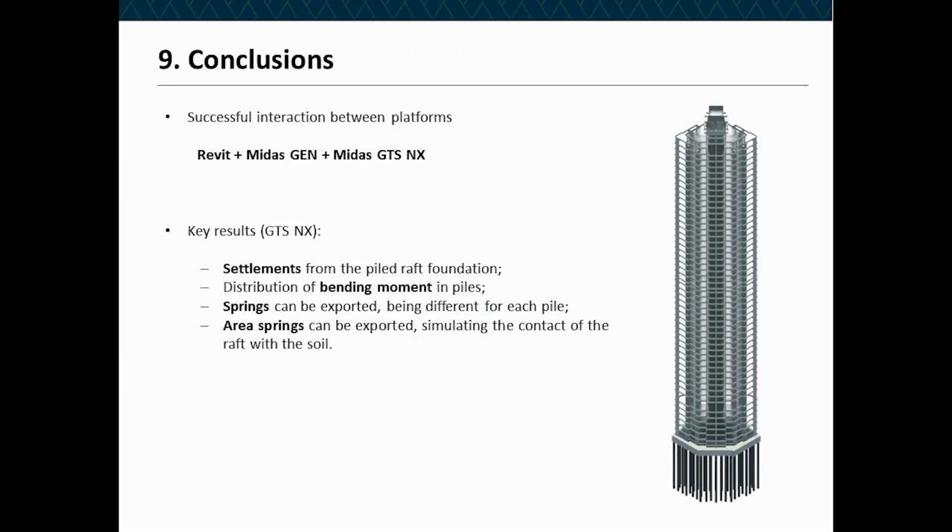Well, for some conclusions, we consider that we had a successful interaction between Revit, MIDAS Gen, and MIDAS GTS NX. The key results from MIDAS GTS that we have analyzed are firstly the settlements of the pile raft foundation, which might be inside the range of the tolerable settlements for this kind of structure. For interaction with the structural team, springs can be created either for each pile and also as area springs, which are the contact of the raft with the soil.